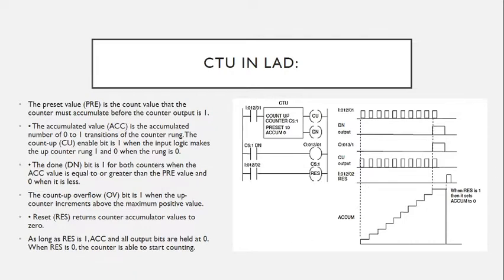Now this part is taken from the book, and this is one example which I'm going to ask you to do in RSLogix, and this will prepare all of us to look at counters in a bigger picture. So we have the CTU block here, and you can see that we have one input. You can name it whatever you want, and this input is connected to the enable pin of the CTU, CU, and then we have the done pin here.